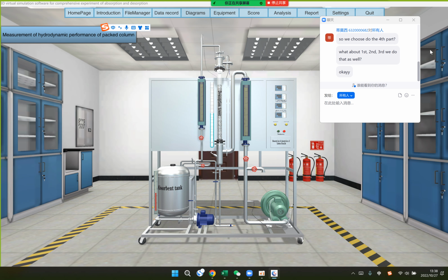But not all the carbon dioxide can be absorbed, not even the ideal or equilibrium part can be transferred from the gas to the liquid. Only some part of the carbon dioxide can be transferred. So in that case, we have to find the mass transfer coefficient for the device, and how we define it is something we have to calculate.